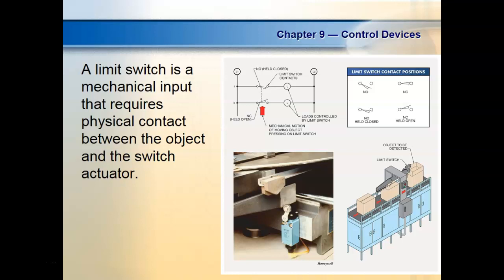Keep it away from a lot of heat. I've seen these things at the top of a furnace, but all the heat from the door just comes up, and we're replacing those things all the time. You could have put a little actuator on the side of the door and mounted it on the side. You would get to it, so it all depends on how you mount them. I think your textbook actually covers that.